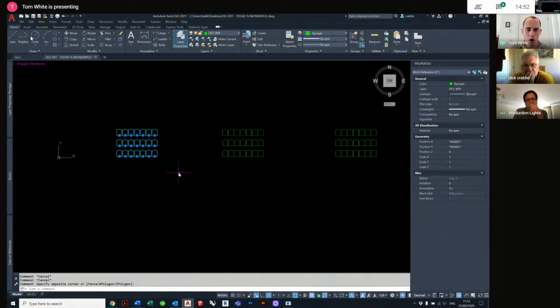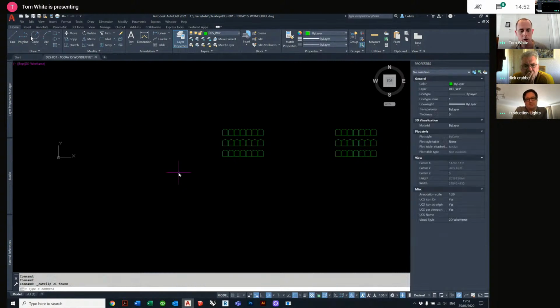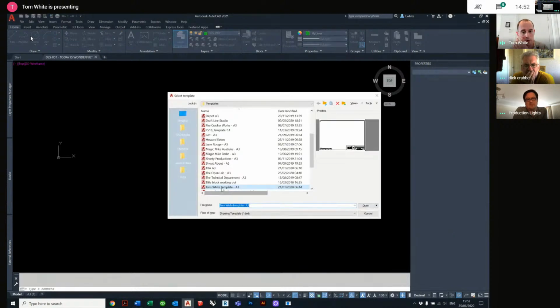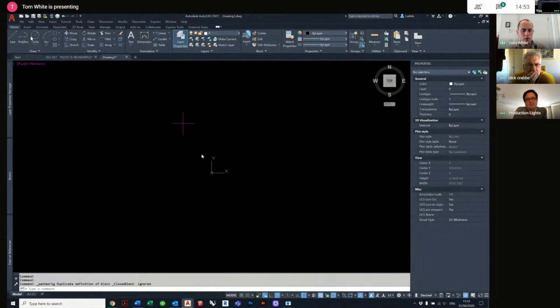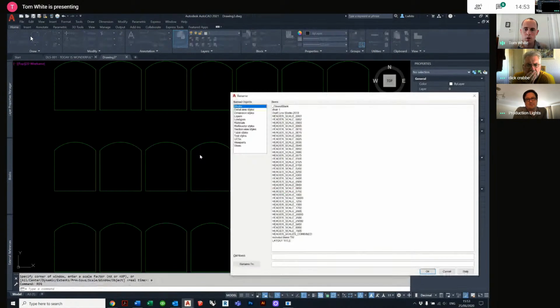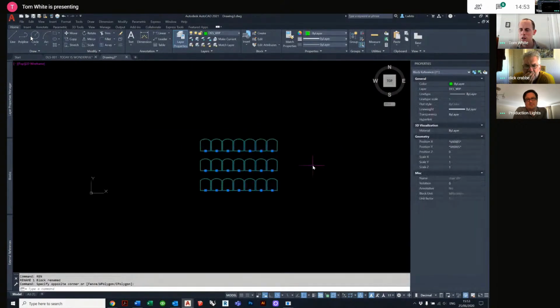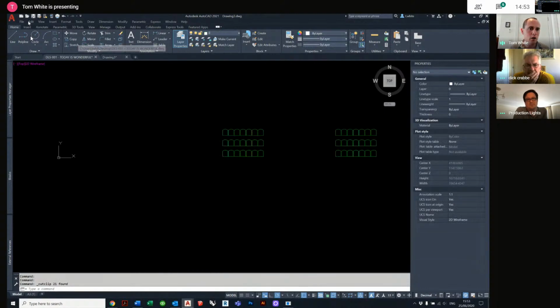So I can explain how I would go around this, and Dom might have a different way of doing it. In this circumstance, I would do Control X to take VIP room 1 away from this drawing, do new drawing, a blank template, go to model space, go to edit, paste to original coordinates, Z enter, E enter, rename command, find chair 1, and rename it chair VIP. I now have in my hand 21 instances of a block called chair VIP, even though visually it is identical to chair 1.